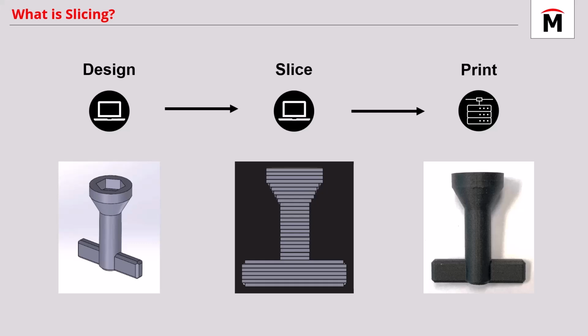You're going to need some type of CAD file, but we can't go straight from the CAD file to 3D printing because the CAD file and the printer don't really speak the same language. And so we use a slicing software to translate the CAD file into something that the printer understands. And slicers got their name because they essentially slice a 3D geometry into a series of layers that stack on top of each other to form a part. And they also send a variety of print settings like temperatures and material flow rates and movement speed, just to name a couple of them.